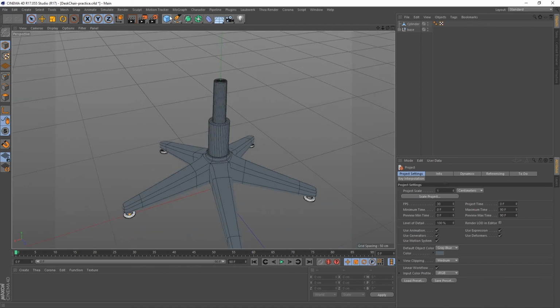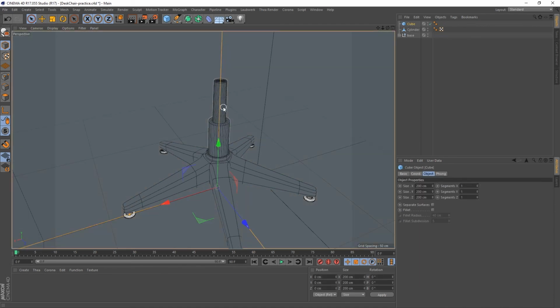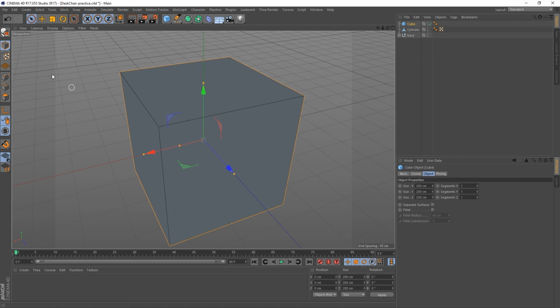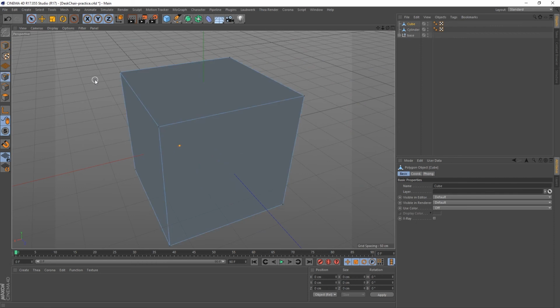We're going to place a cube. Hit S to zoom out to it. Hit C to convert it, and hit Enter to go into edit mode. And again, click middle mouse button and drag. Make sure the live selection circle is bigger or smaller. So now, when you paint with that, then it'll select whatever is inside there. A difference with the window select tool.